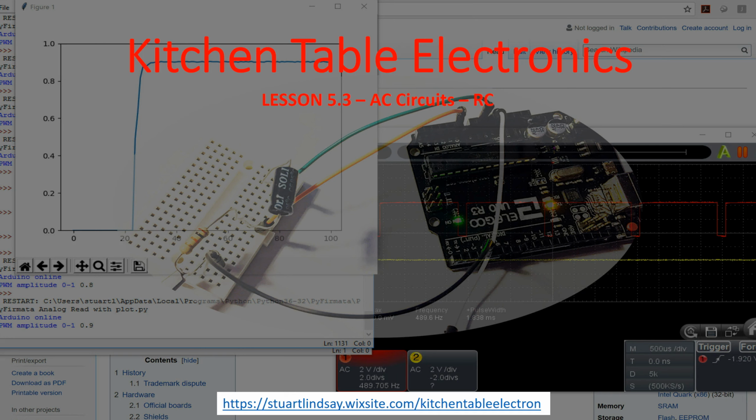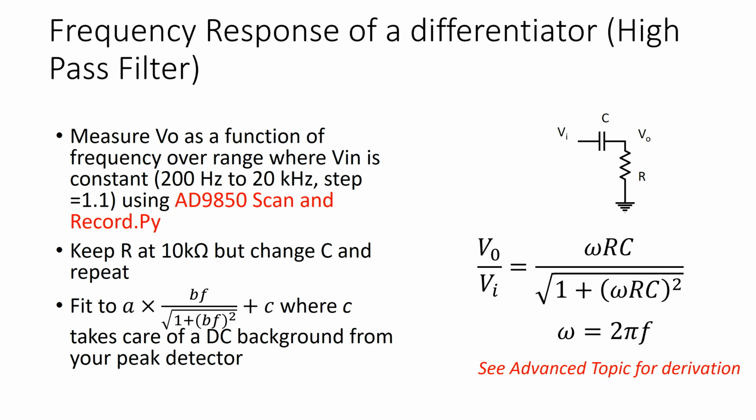We're going to look at circuits composed of arbitrary values of capacitor and resistor and over any frequency, and we're going to do this using complex analysis of the impedances, the derivations of which are explained in the accompanying advanced topic for Module 5. So let's begin with a high-pass filter. This is the differentiator that we looked at in the last lesson. So a capacitor connected between the signal source and the signal measurement point here, and a resistor to ground.